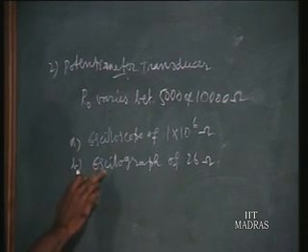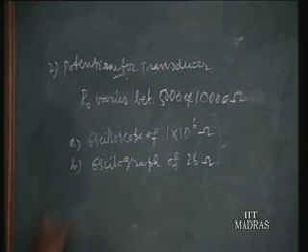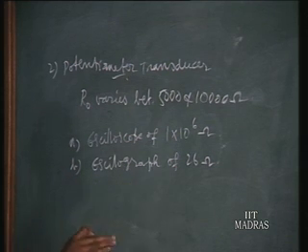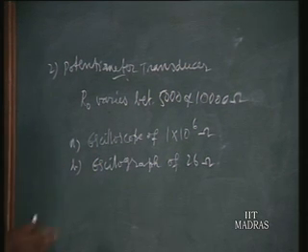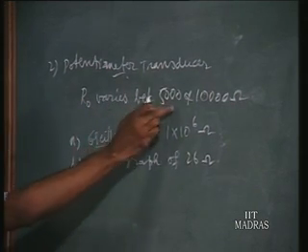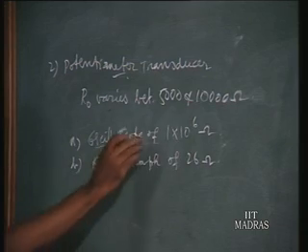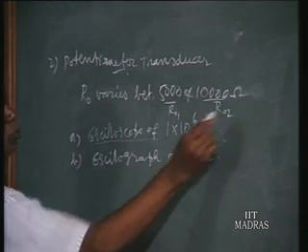And there are two types of instrumentation. One instrumentation is the oscilloscope, as in the previous case, and the second instrumentation uses the oscillograph to record the output voltage. Now what is the loading effect in these two instrumentations separately? Take the first case, the oscilloscope. Because RO has got two extremes, the loading effect also is varying between the two extremes. We call them RO1 and RO2 in the two instances.